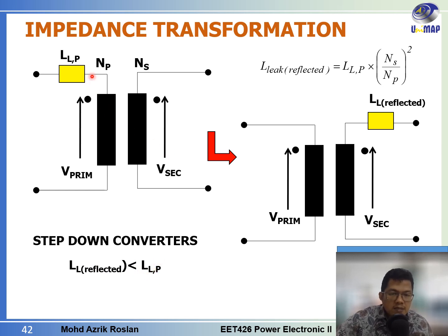In the analysis of the leakage inductance, we don't want the value to be on the primary side. We want to transfer everything to the secondary side because we are interested in seeing the effect at the secondary side, where we have the output.